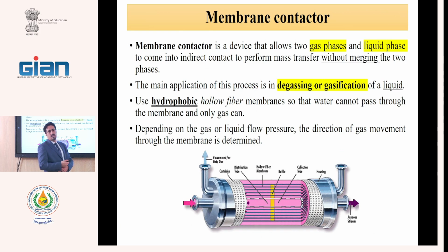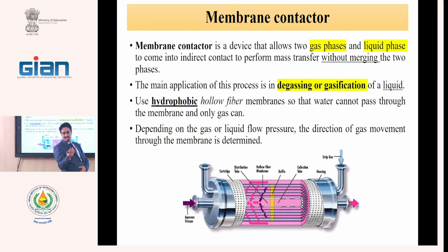Therefore, natural gas companies separate the carbon dioxide and H2S from the methane with an absorption column, where we have an amine solution that can absorb acidic gas. H2S and carbon dioxide are acidic gases, and amine is basic and can absorb these acidic gases.